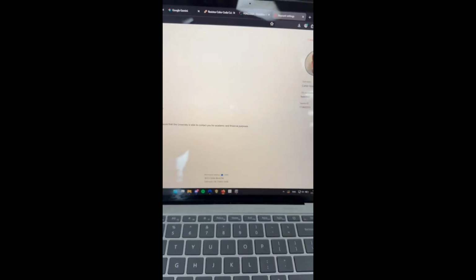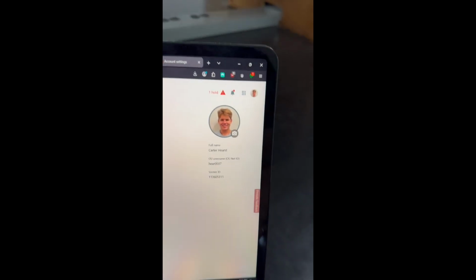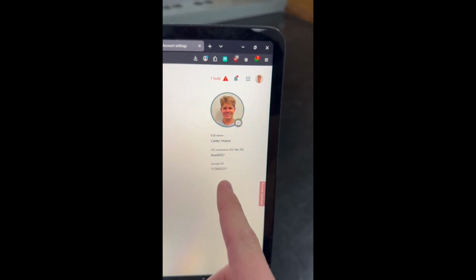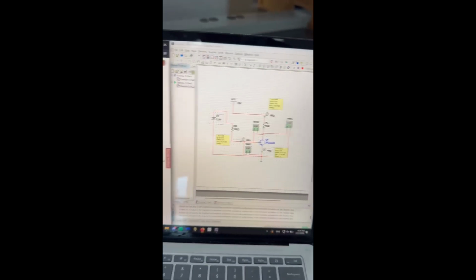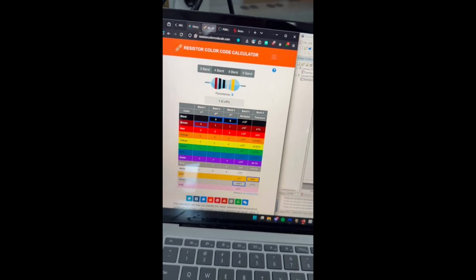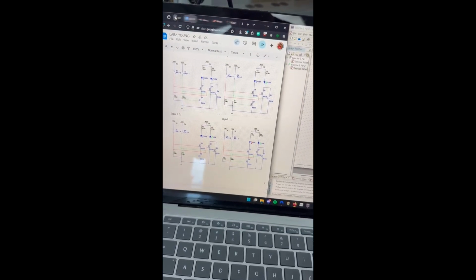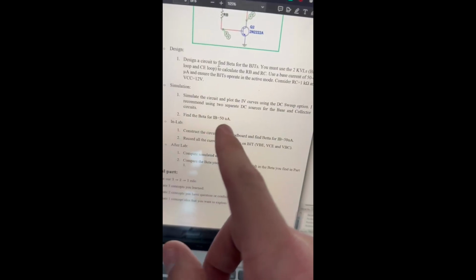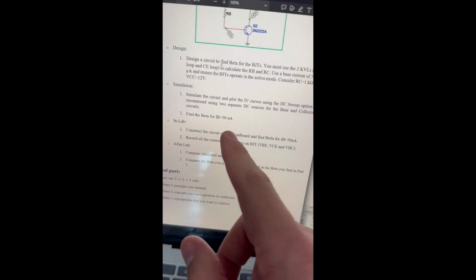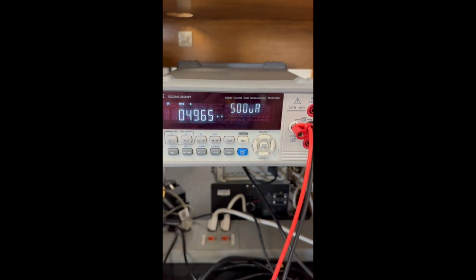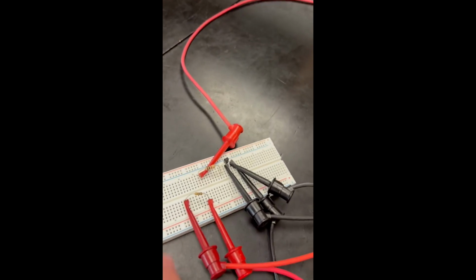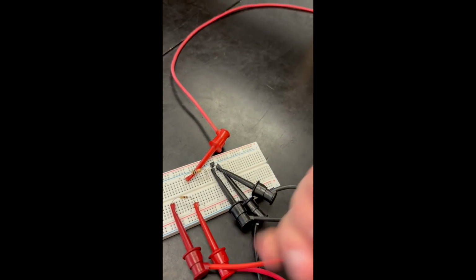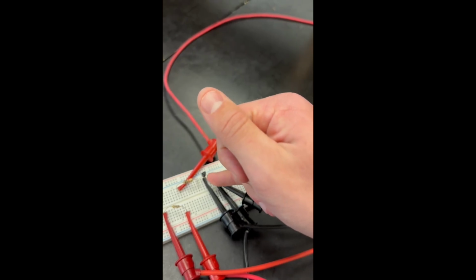This is Carter Hurst on exercise 3, part 2. 113-605-311. There's my Multisim. So I'm trying to find the 50 microamps through the base, IB 50 microamps. I got it to 49.645, pretty close in the microamps, which is connected through this resistor. It's 100 ohm